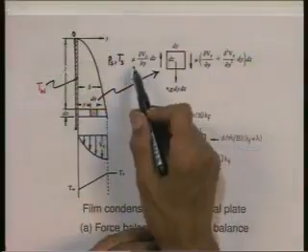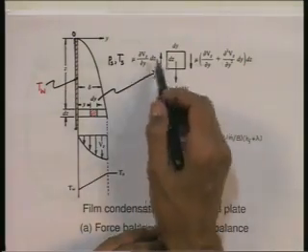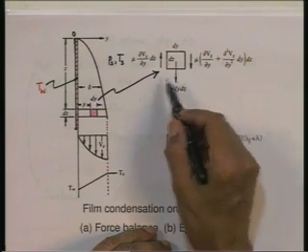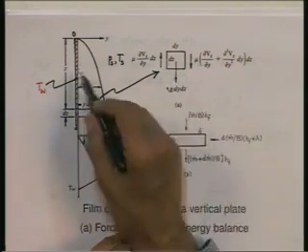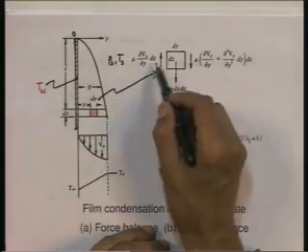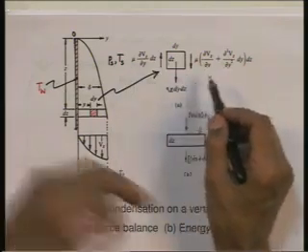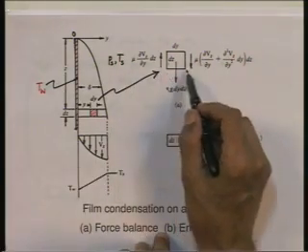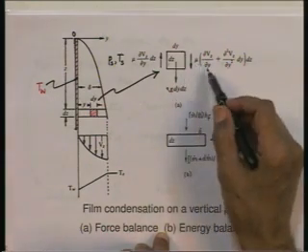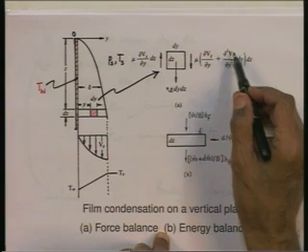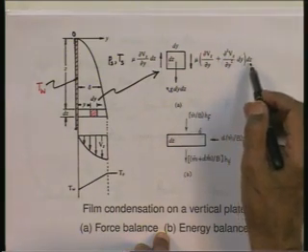On this face it will be mu dvz/dy, this is our Stokes law relating stress and rate of strain, and on this face, because I have moved a distance dy forward in the y direction, this mu dvz/dy gets increased by a certain amount. So, it becomes mu into (dvz/dy plus d2vz/dy squared into dy), the whole thing multiplied by the area dz.